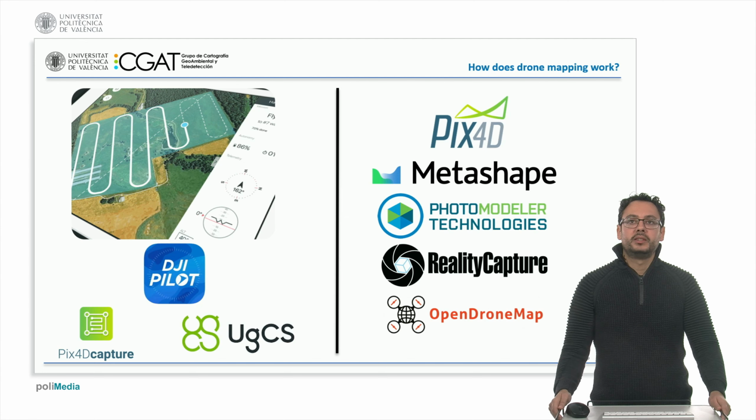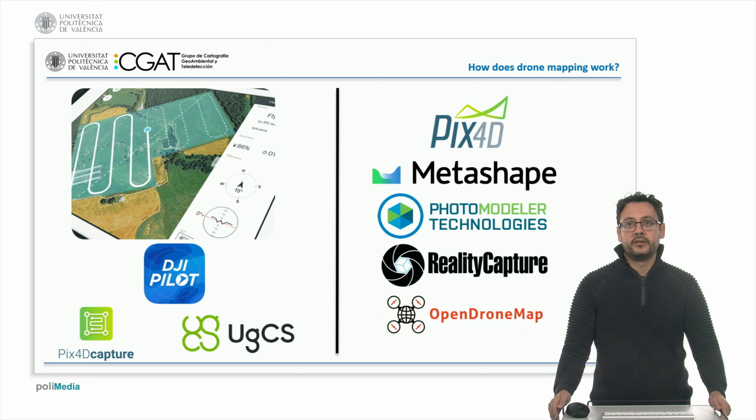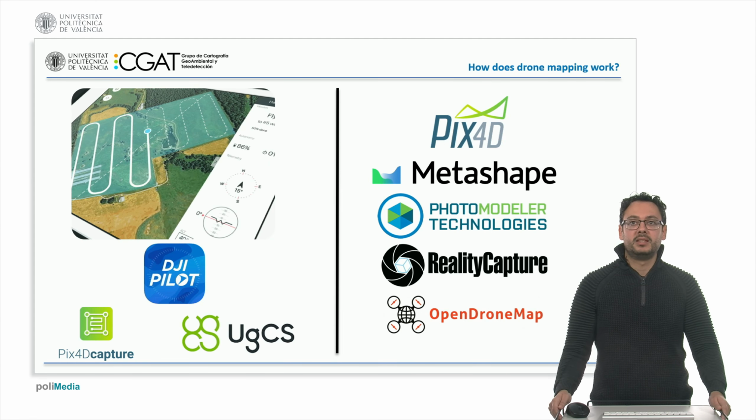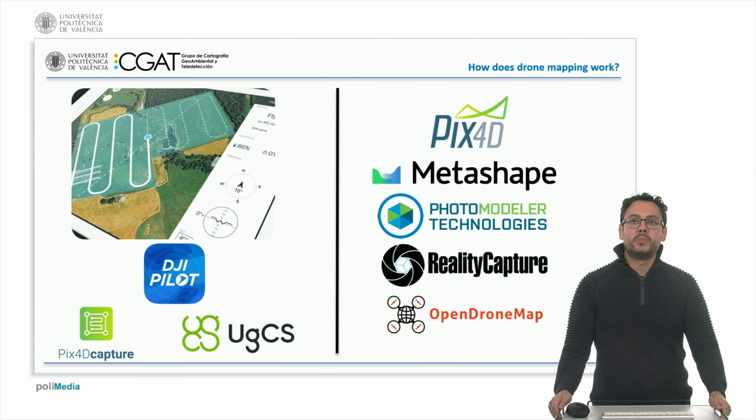To perform a photogrammetric survey with a UAV, first, control points are positioned on the ground over the study area, and their centers are measured with GPS. Next, a flight is conducted in which there is at least a 70% overlap between the photogrammetric shots, both frontal and transversal, whereas in complex environments higher overlap is required.